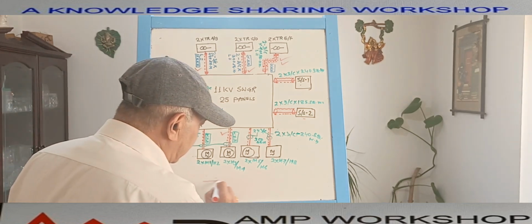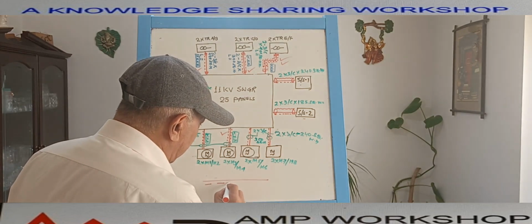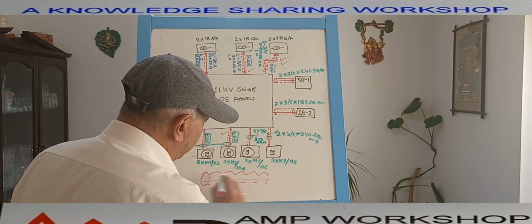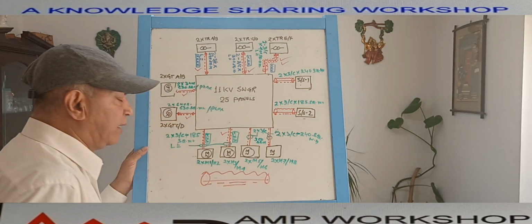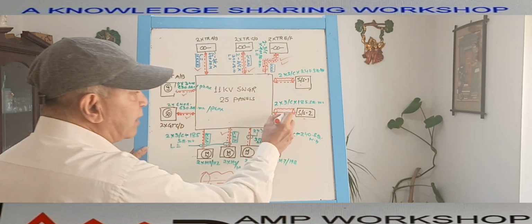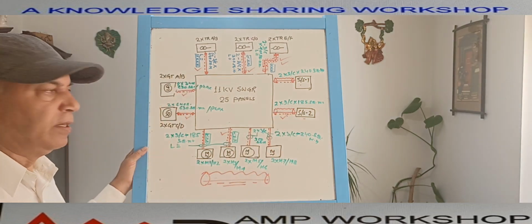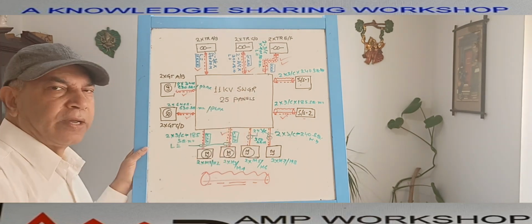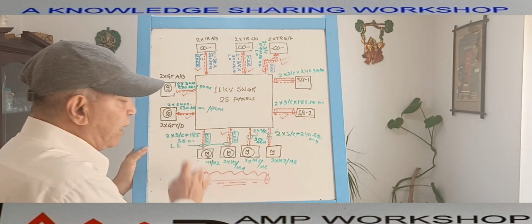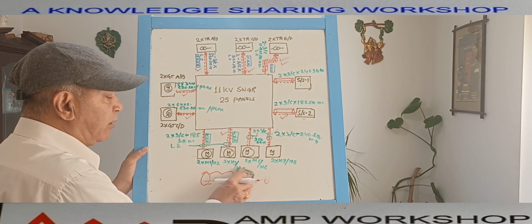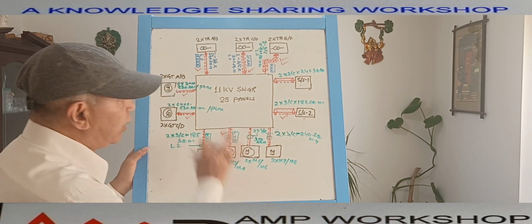For that symbol, this is the cable, the bottom is a dotted line and the top is wavy. Wavy means it is a water wave. If we represent it this way, you understand this cable is under the sea. This is a subsea laying cable, directly laid on the subsea bed. So these are the 4 different ways the cable can be represented to show its laying method. Here we have considered 4 different methods.